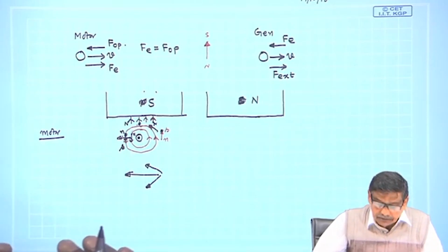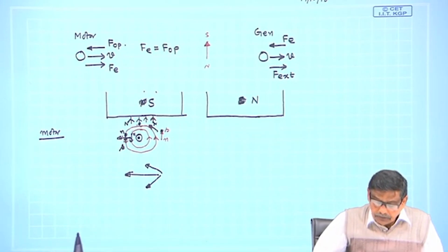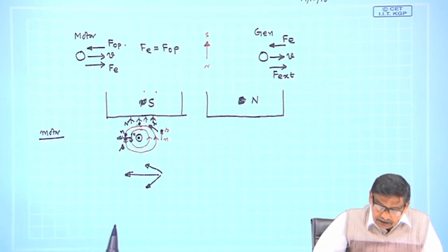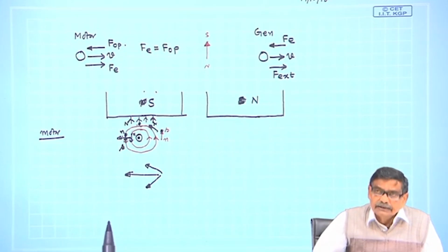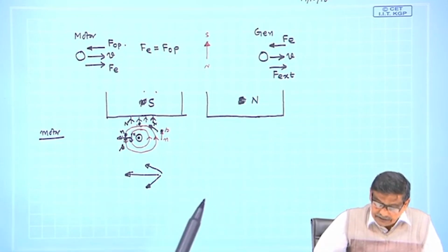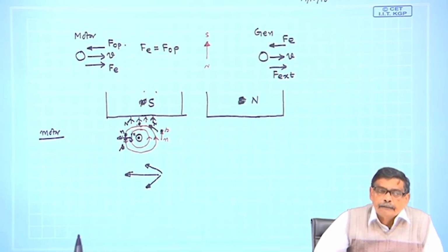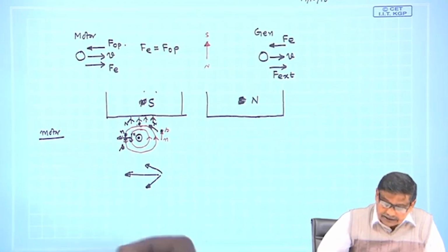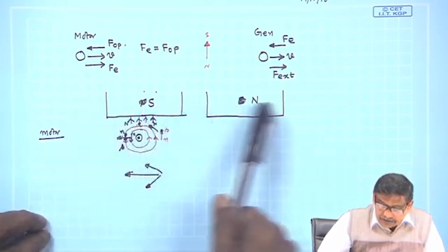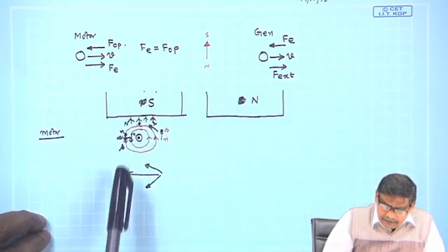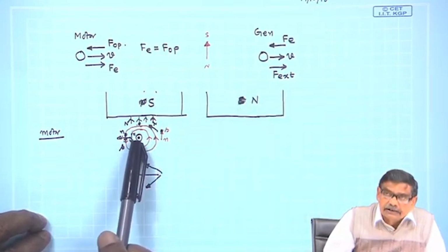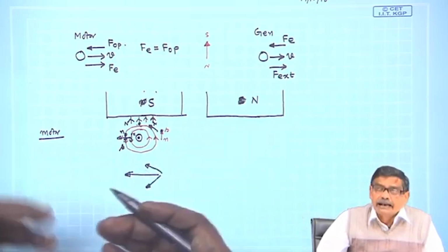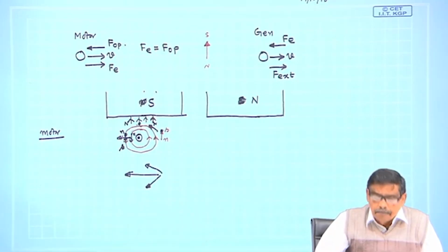In other words, what I am trying to tell is, to know the direction in which the conductors will move, one can imagine that ultimately it can be traced down to the fact that two sets of magnets are interacting with each other. One set is produced by this structure which is not moving, south, north, whatever it is, and the other is the conductor which is supposed to move, be it motor or generator, but it will carry some current at a given instant of time.